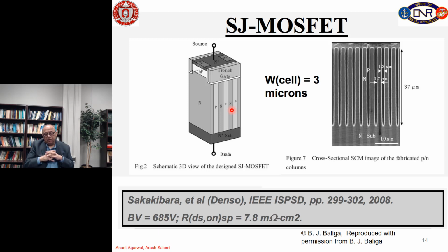Again, in silicon carbide we haven't figured out how to make them. The implant regrowth becomes very difficult in silicon carbide, but perhaps etching the trenches and filling the trenches by epitaxial growth is a way to go. Several research groups are currently working on it.